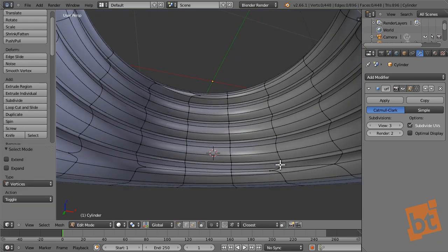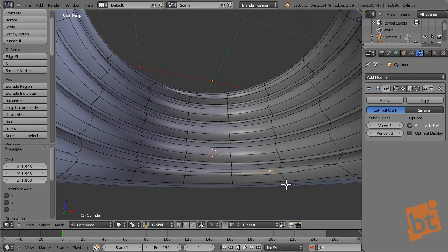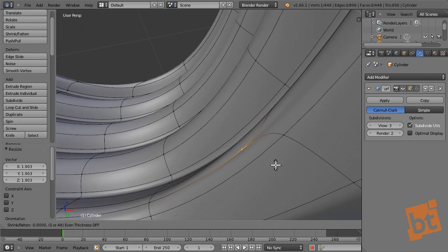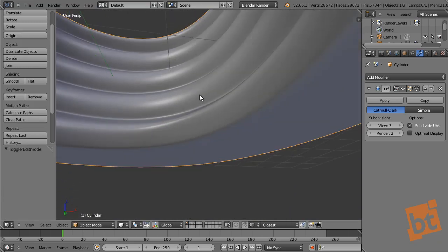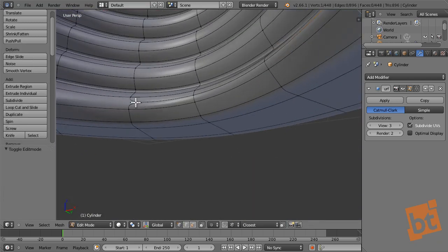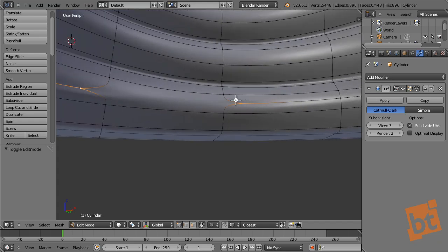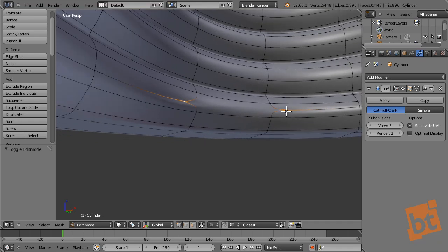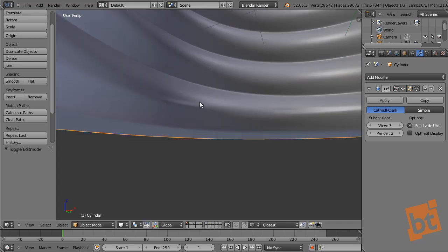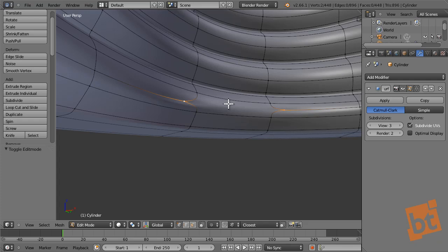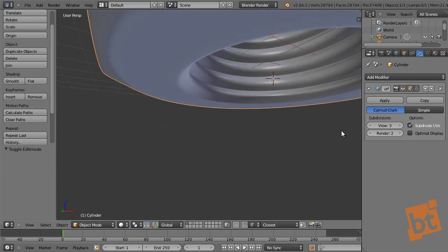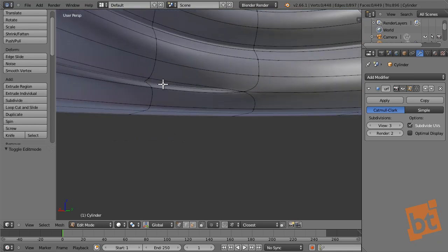And now we can just arrange this a little, scale this up and get closer and scale this with Alt S a little out, like that. Okay, and these ones I just dissolved it and I didn't arrange it, so we can select these two vertices. As you can see, we have some pinch in there, and that's why you shouldn't use triangles or n-gons. Right, here we have an n-gon, and this is the result. All right, we have pinches in the two sides, so we join this and we already have a quad there. Pretty nice. And now here we need to solve this.